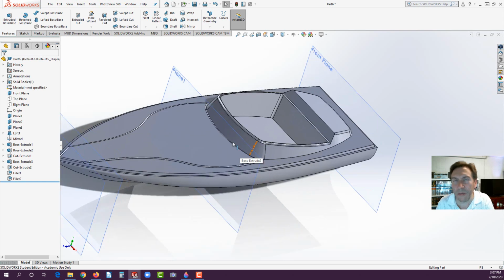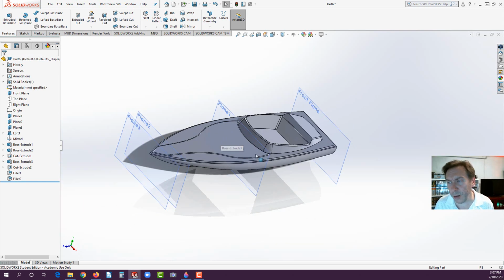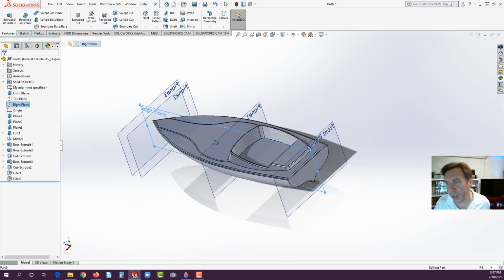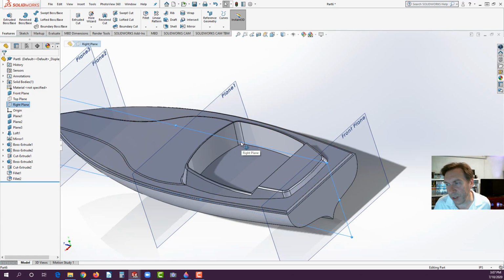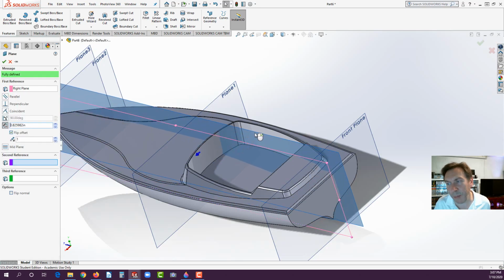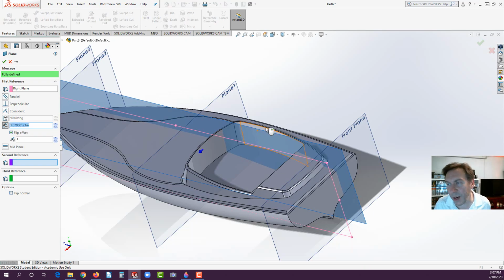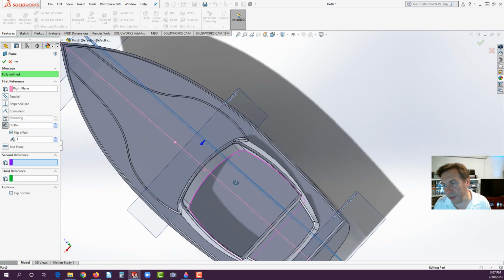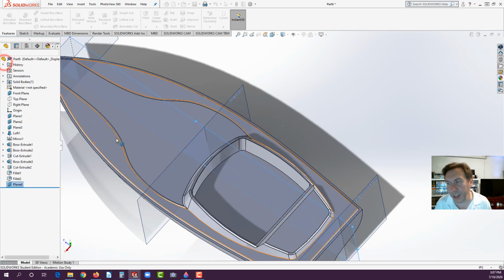Okay. Now, if some of you are wondering how to get a steering wheel. The steering wheel, say we want to offset it, we don't want it in the center, you would select, and I'll show your right plane. There's my right plane. And I'm going to hold control and drag off a copy just like we did before. And I'm just eyeballing, in this case, maybe about an inch. Yeah, we'll just make it an inch even. See it's offset there. Hit the green check.